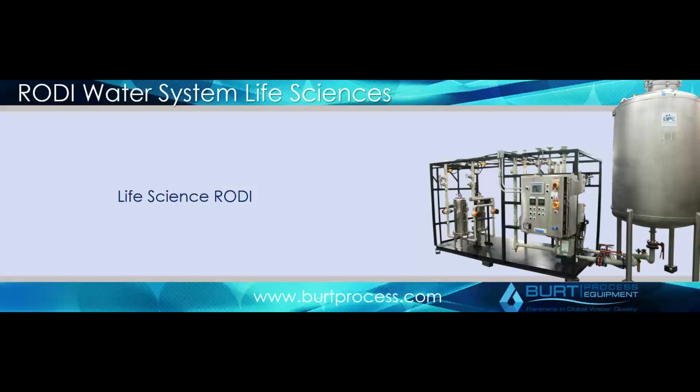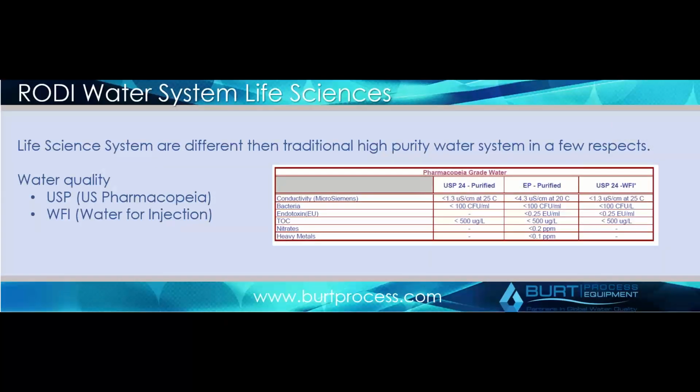Life sciences for high purity water has its own little requirements. It's less concerned about things such as, like I said, resistivity and TOC, and it tends to focus really between two different parameters: USP, which is US Pharmacopeia, and then WFI, which is water for injection. As you can see here, the water parameters are a bit different. For USP 24 purified, you're looking at 1.3 microsiemens, which is like 0.1 resistivity, as opposed to the one we just looked at, where you're looking at 18 megohm.